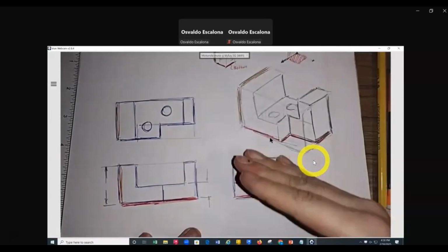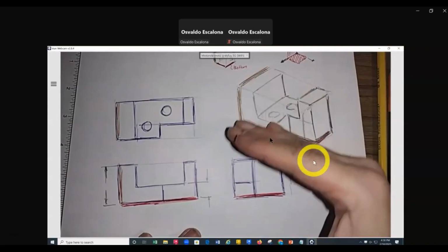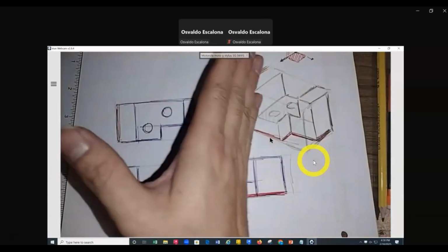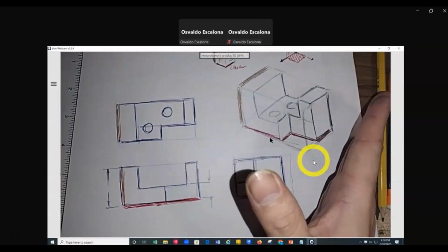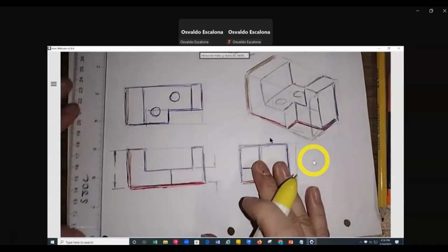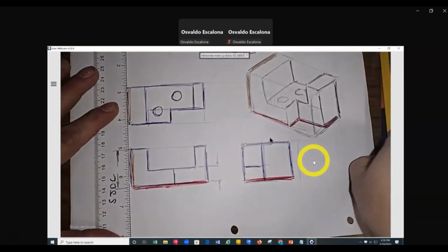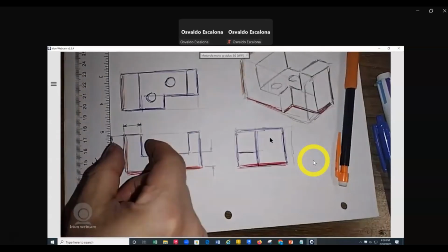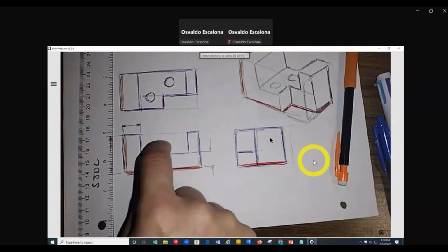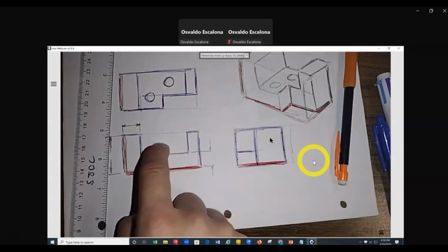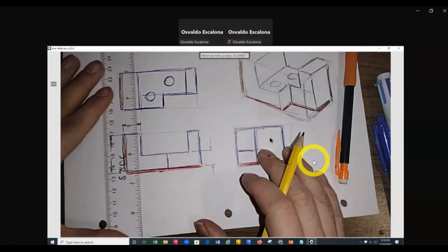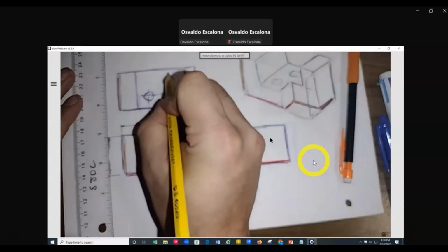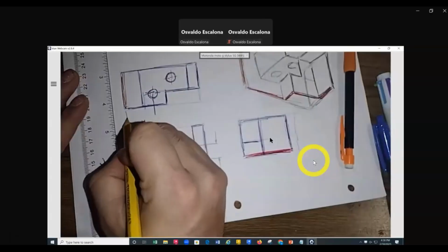And as I did before, I went from the bottom to the top. I saw the thickness, I saw the height. Now I'm going to go from the left and move towards the right. I'm going to go from here and look at each of those features. Boom. That's the first feature I see. You are like, Professor Corona, why did you put it on the bottom? Because that's where I can see the thickness. That's where the notch occurred. That's how it got manufactured. Thumbs up? Next one. Boom. Bullseye, center lines, right? To the bullseye. Boom. Why did I put it on the top?